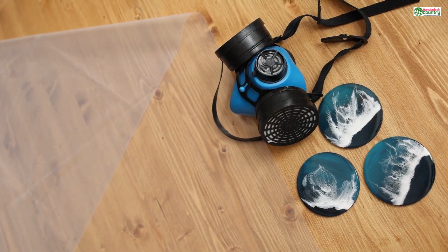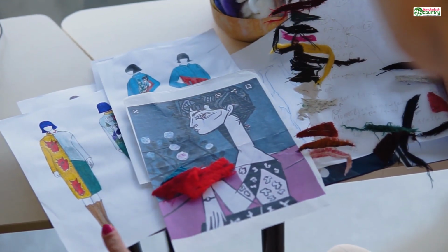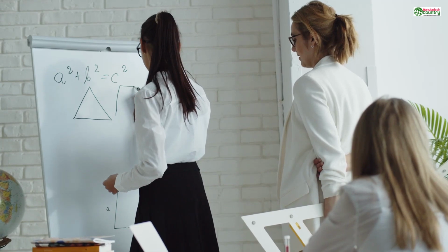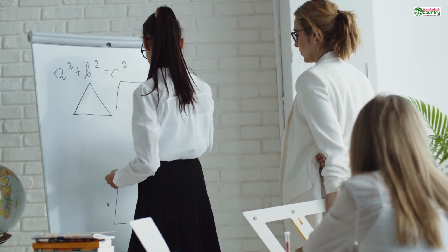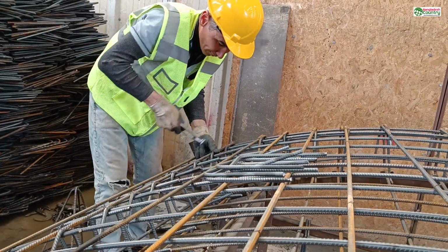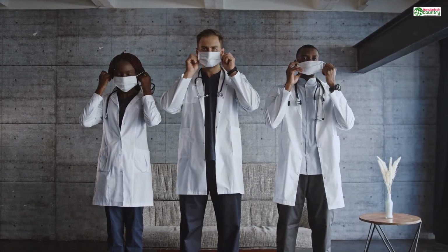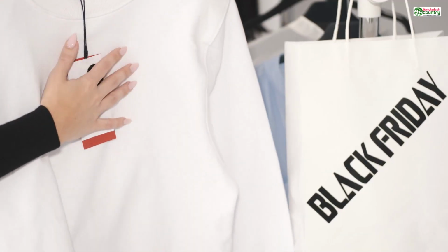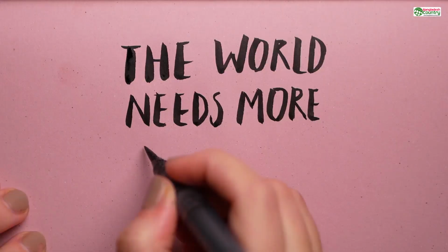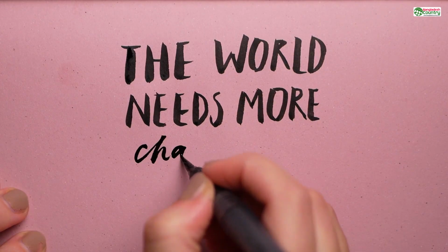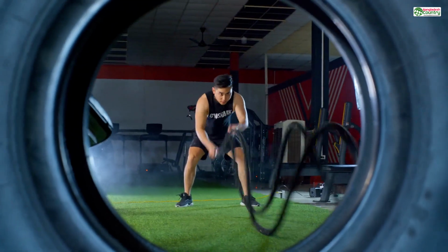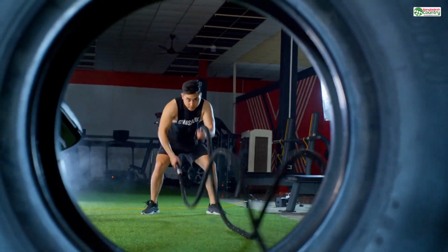These are the reinforced sculptures. They are specialty resins engineered to mimic the mechanical properties of plastics like ABS or PETG. They offer that same stunning surface finish and fine detail, but with much higher impact resistance and strength. If you need a functional prototype that also looks injection molded, or a final use part like a custom jig or enclosure that requires both a perfect finish and real-world durability, these advanced resins are the answer.